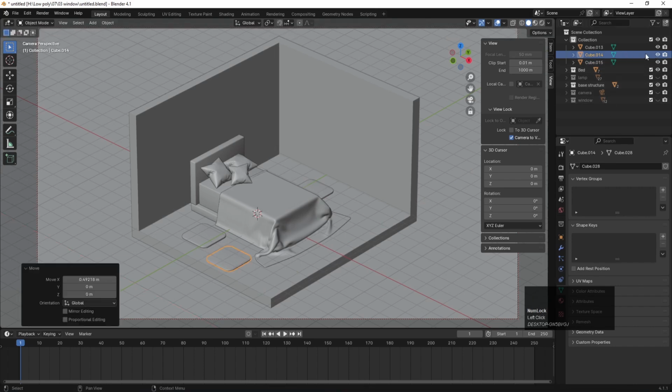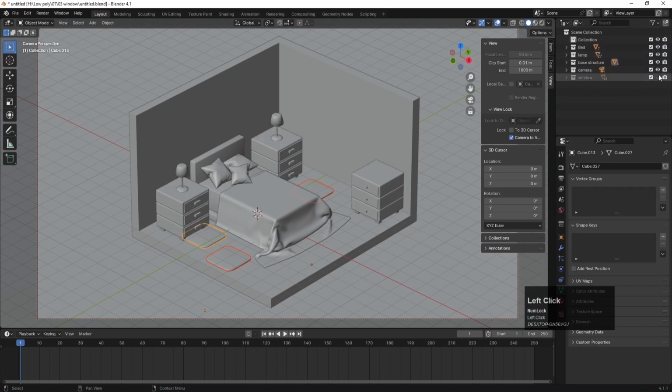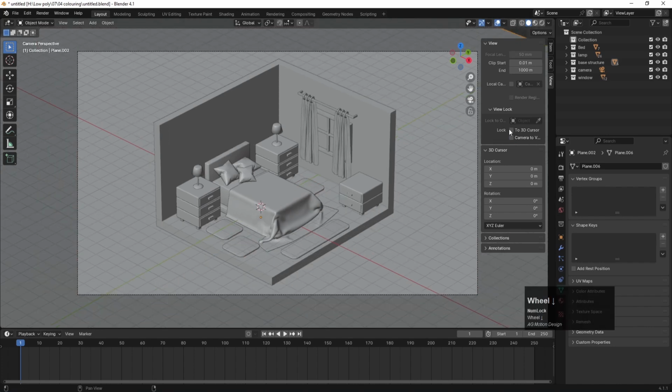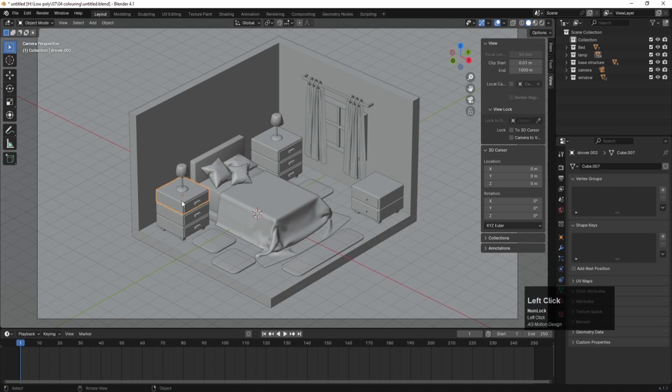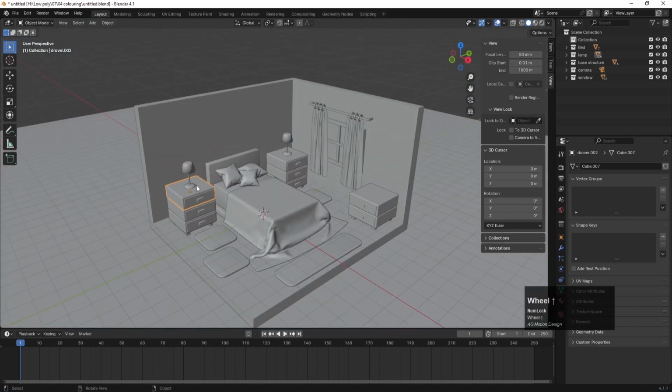Let's enable this. Let's select all of this cube and we will move inside this base structure. Okay, let's enable all, and our model is ready, and now we will apply textures to it. So now we will try to give colors to our animation over here. Make sure that this option is unchecked because you don't want to change the position of your camera. Okay, and let's hit 0 to go out of the camera view like this.